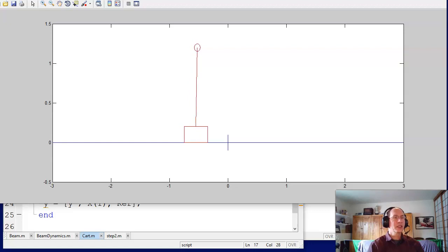So what the integrator is doing, the servo compensator, it is trying to figure out the sine, cosine, how much is sine, how much is cosine, what's the amplitude, whatever it takes to cancel the disturbance, and it's trying to figure it out, and looks like it's just about figured out what I need to apply to cancel the disturbance. Then the output tracks the set point, which in this case is 0, meaning I'm rejecting a sinusoidal disturbance.